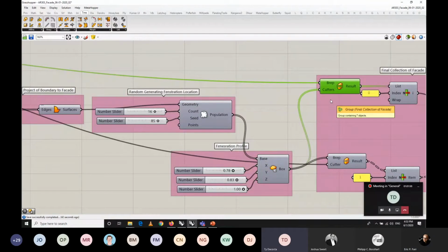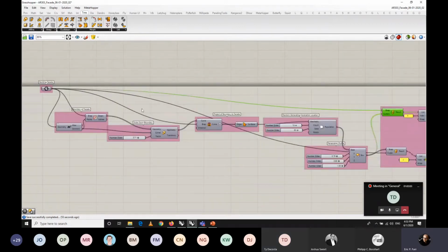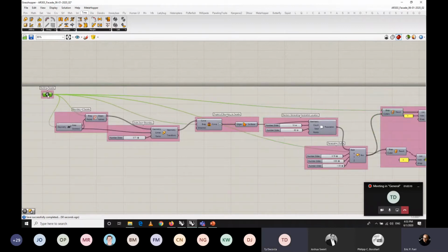It's just creating multiple surfaces. You know, there's the artifacting when there's multiple surfaces on a single plane. Probably because you have multi-surfaces in here. So start with one surface, and then try it with one surface, not multiple surfaces in here. If you're using more than one surface, probably you're going to get some issues in here. This can be one of the reasons actually.